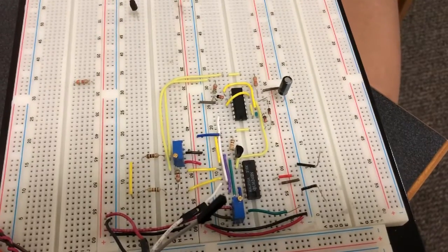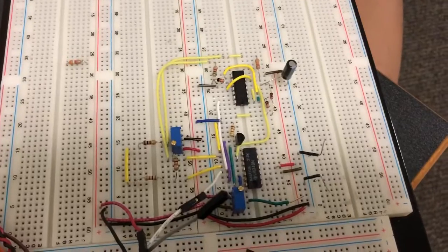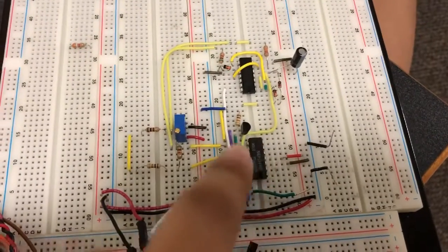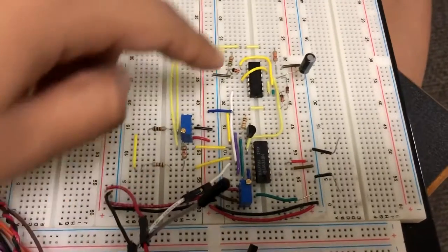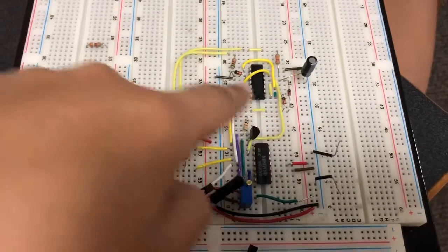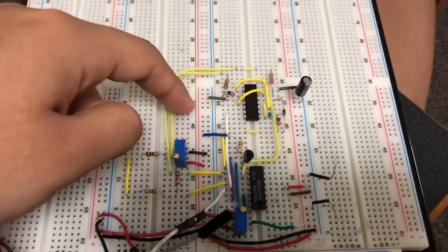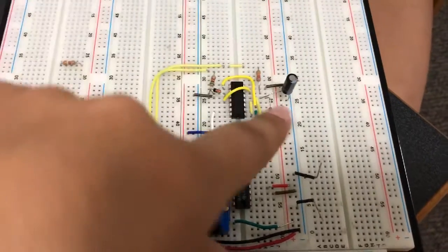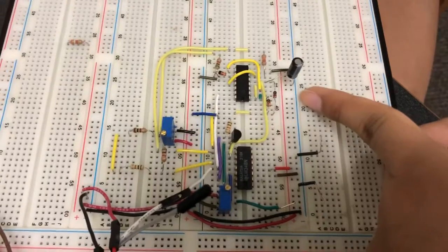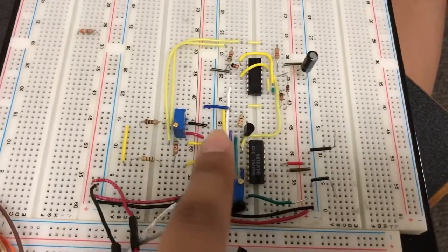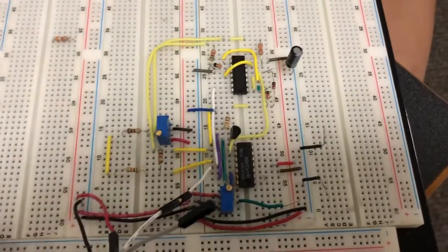So altogether here we have our completed VCO circuit. So once again, here we have our current source. Here, this is our Schmitt trigger. Over here is our current mirror, and then here we have our inverter. And this is the capacitor, which we measure the voltage at node A. And then here is our output of the Schmitt trigger.